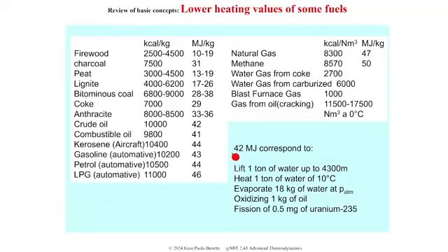That number corresponds, as we've seen in this waterfall example, to lifting 1 ton of water up to the top of Mont Blanc from sea level. The same energy is what is needed to heat up 1 ton of water by 10 degrees Celsius, or to evaporate not 1 ton, but 18 kilograms of water at atmospheric pressure. So that's also oxidizing 1 kilogram of oil.